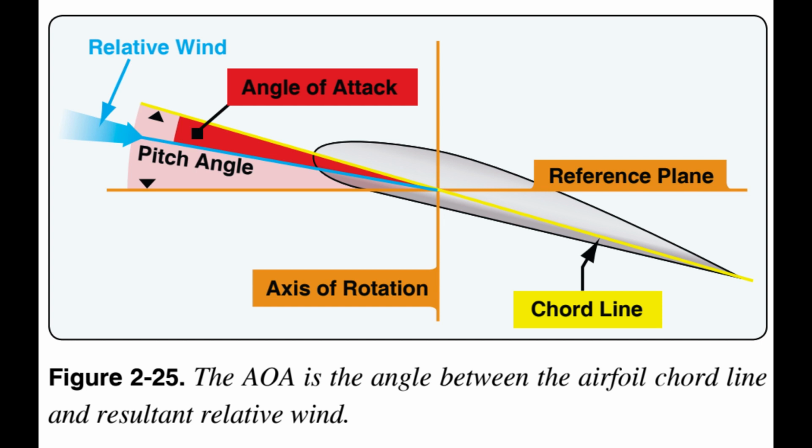Flapping is the up and down movement of rotor blades about a hinge on a fully articulated rotor system. A semi-rigid system does not have a hinge but flaps as a unit. A rigid rotor system has no vertical or horizontal hinges, so the blades cannot flap or drag, but they can flex. By flexing, the blades themselves compensate for the forces which previously required rugged hinges.